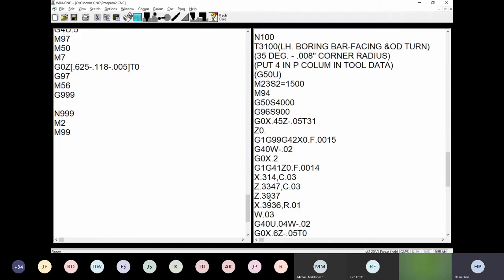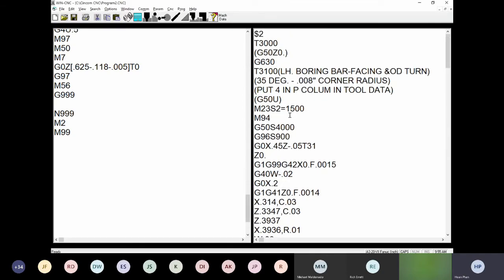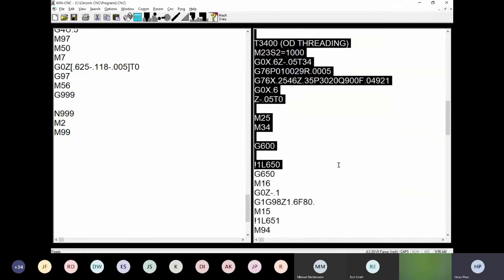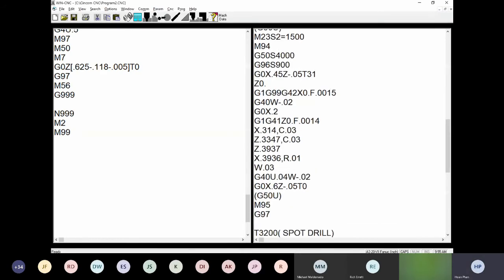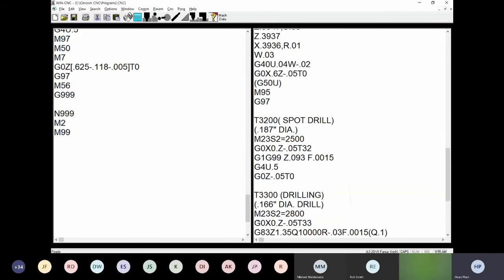and put it down here. So on top of right here, you don't need to have too much code anymore, because it's gonna make your program long and not looking professional. So you can just delete this right here and then put in here M98H100. Okay, and remember, in order to get a loop back, you have to put M99 at the end of the program in order to loop back wherever it was before.